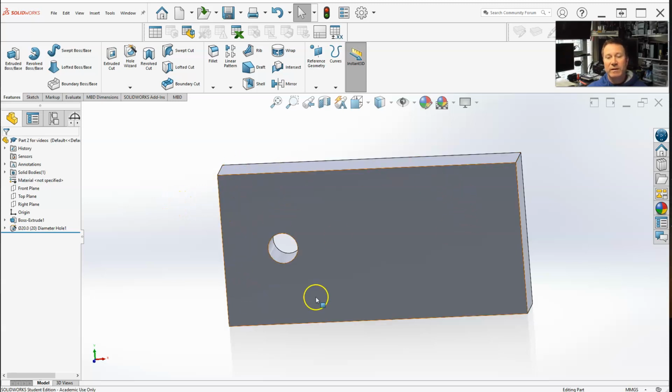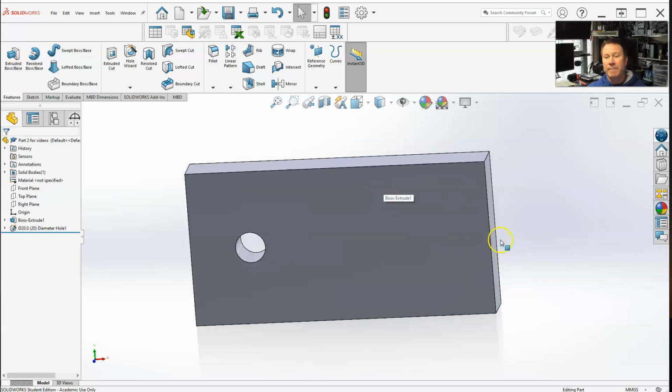So I just created this part, and actually following my own advice after I did the first example in the actual pages, I created just a rectangle with a length and a width, and then a diametric hole, a through hole, to separate. So I have two different variables. I have basically two features. One's the first extrusion, and the next is actually creating a hole. That way I can show you some other features of suppressing certain things later on.